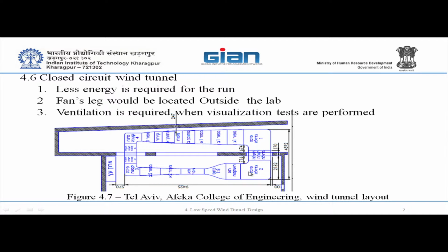Following the fourth corner, you have the settling chamber, constant area, which will include all your attenuating elements, be it honeycombs, meshes, whatever you put there. And that's it. And then the nozzle, most important, I forgot to tell you. In the Tel Aviv case, the ratio was almost 1 to 8, or 8 to 1. We'll elaborate on the nozzle later on. So we'll have a break.